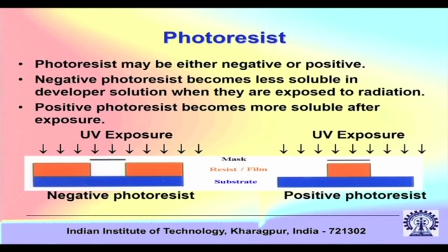Now on the SiO2 layer combination, we coat with a photoresist, that is the next level of coating, before we shine a light source on the entire system, masked by the mask with certain patterns. The photoresist is deposited by a process called spin coating. There is a device called a spin coater which deposits a thin film of the photoresist on the substrate.